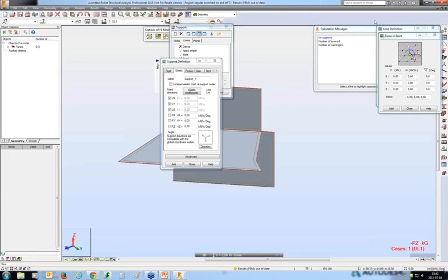Okay, so we still have a few more questions that are being answered. Again, maybe slightly off topic, but I'll read through those, as now that everybody's got the chat window, they'll be able to send us more questions. One that came in earlier that Guillaume answered: I want the panel to update when I move the geometry of my nodes manually. And the response is, when you manually move mesh nodes, mind that you merge the nodes with the structure correction tools as shown in the presentation, then freeze the mesh and run the model generation.